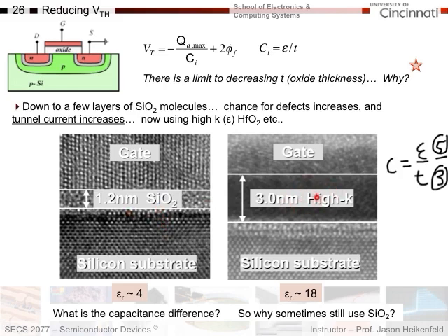With something like hafnium oxide, you need to actually add it to the substrate, deposit it down, and there's a chance that if there's a speck of dust or something on the surface, it gets trapped in there and creates a defect. That increases your chance that you would lose a whole computer chip because of one little defect. So this was hard to do. This was not easy.